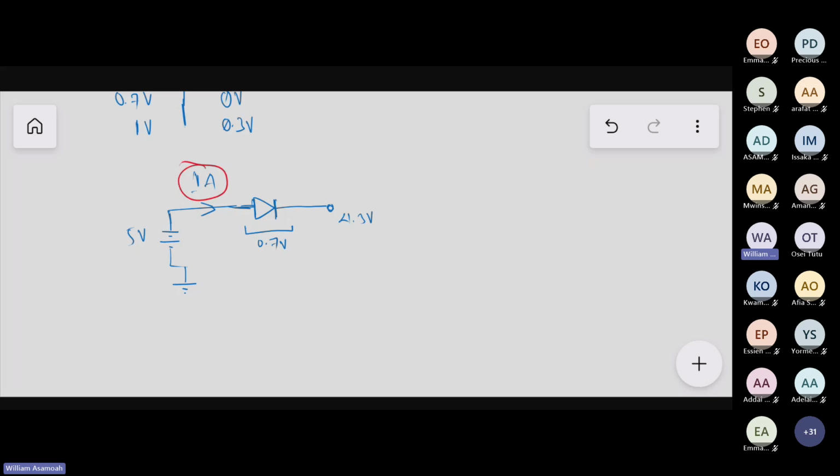The maximum voltage of an AC is 325. That means that if you connect the 1N4001 diode to an AC, it will get damaged because the maximum voltage is more than it can endure. By the time you realize, you'll just be seeing smoke. So you first of all look at the current you need. Then the next thing is to look at the maximum reverse voltage. Then you base on this to select your diode.